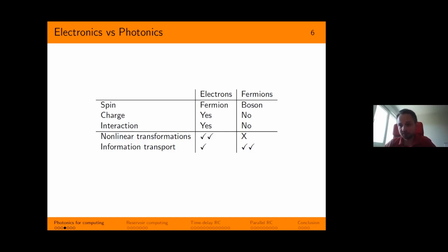Let me give you some figures to illustrate that. The energy just to switch a transistor or to switch a flip-flop in a standard CMOS gate ranges between 40 attojoules to 3 femtojoules. It's a very small quantity of energy. On the other hand, switching an interconnect of 10 millimeters of line consumes 100 times more, 600 femtojoules.